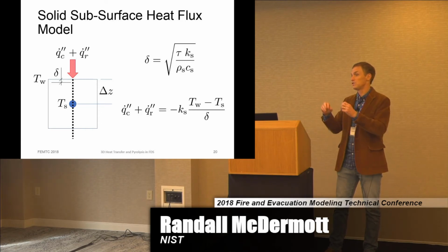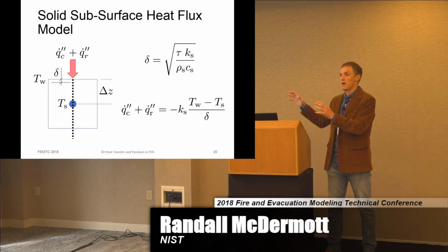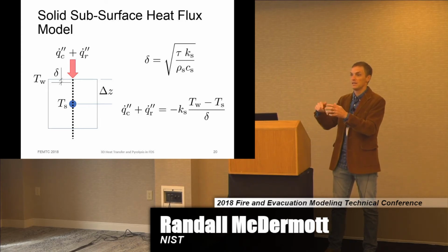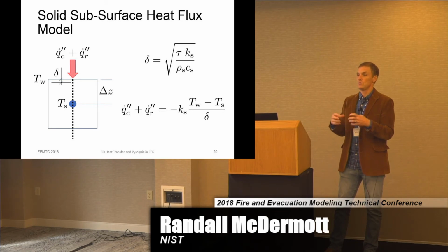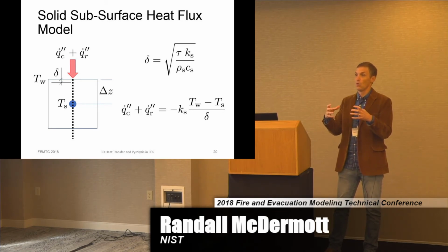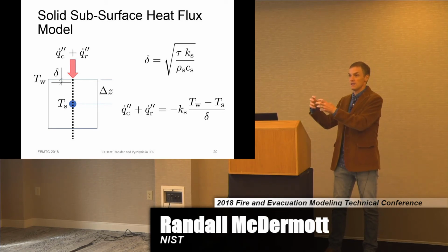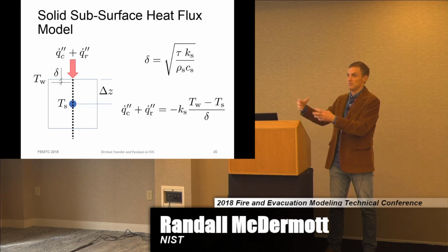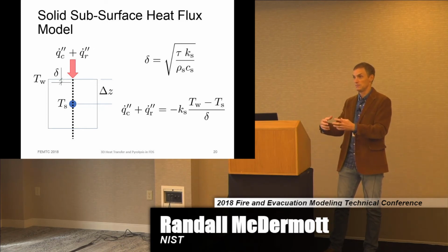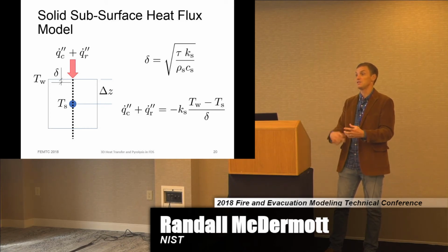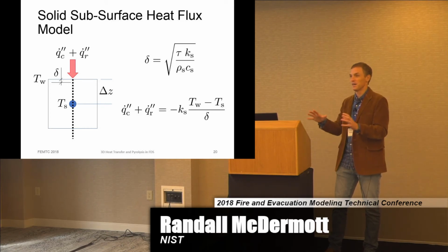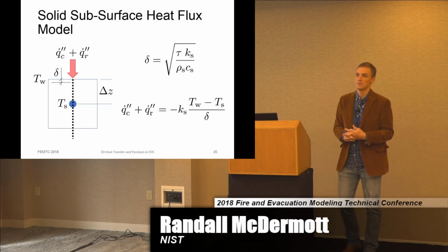If it's just heat conduction through a metal, you can say material ID equals steel or whatever. Or you could say surf ID equals steel, and you could have a surf ID that had steel without a thickness and say material ID equals this, and then you say HT3D equals. This is all described in the guides, the details of those. All right, and there are examples. So. Other questions?